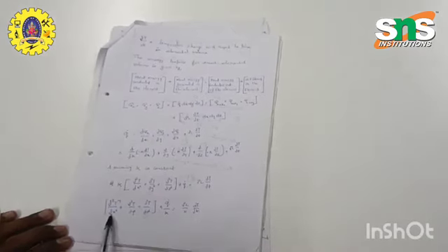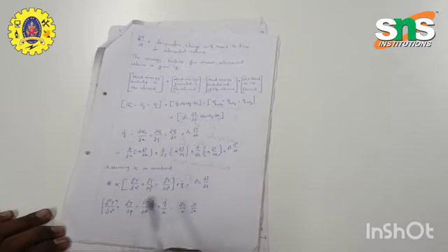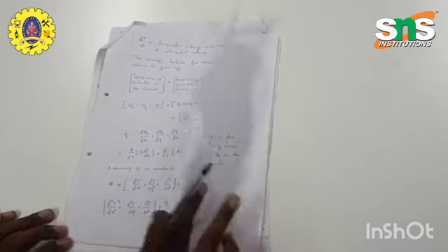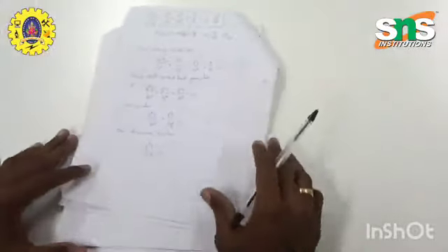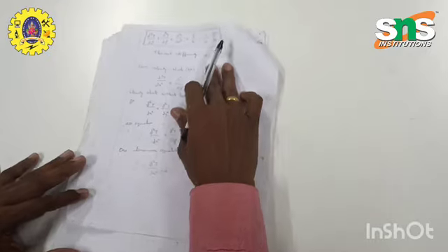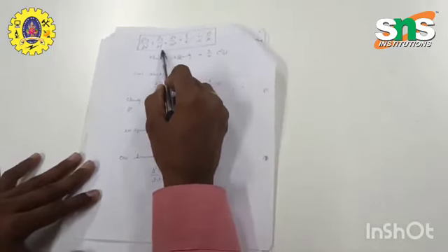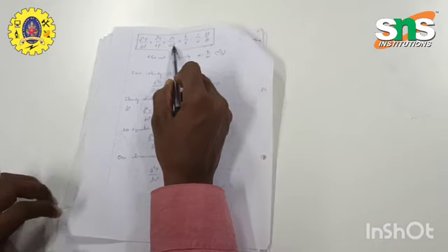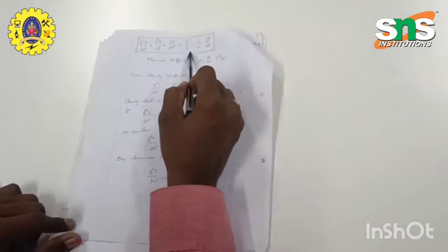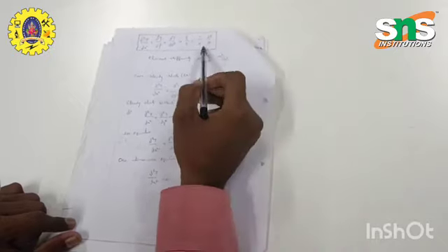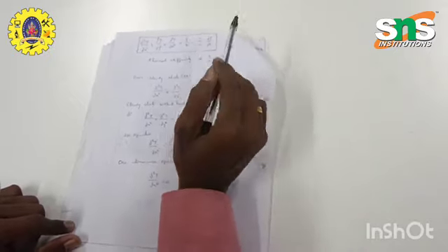So in this term, we have q dot on the right-hand side, and the equation simplifies to the final stage. The final equation of heat conduction is dou squared T by dou x squared plus dou squared T by dou y squared plus dou squared T by dou z squared plus q dot by k is equal to 1 by alpha dou T by dou t. Here alpha is the thermal diffusivity.